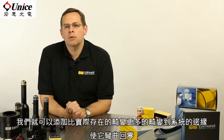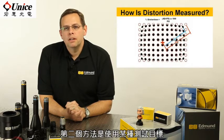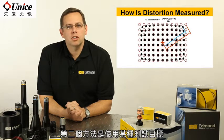Now, if we were to look at the graph where it's actually bending back on itself, if we were to take a distortion measurement somewhere in the middle of that curve before it starts bending back and extrapolated that all the way out, we would actually add more distortion to the edge of the system than is actually there because it's bending back to zero. It's important to know where these curves go when you're trying to factor it out of the system. And there's a couple of ways to do that. First off is you can use the design data that an optical manufacturer might be able to give you to map that out. The second thing is to use some sort of testing target.